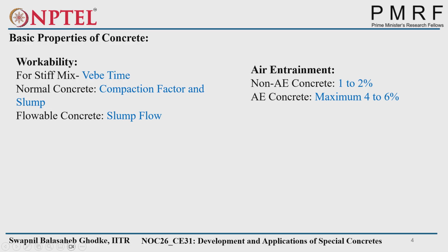And air entrainment. Different types of admixtures are available, like water reducing admixtures, accelerators, and viscosity modifying agents, and according to the requirement of the concrete or casting procedure, we have to use them. But sometimes we have to consider air entrainment also. Anyone knows where we have to use air entrainment as an admixture? Right, cold weather conditions. Cold weather countries like Canada and Norway, wherever we have to use air entrainment.